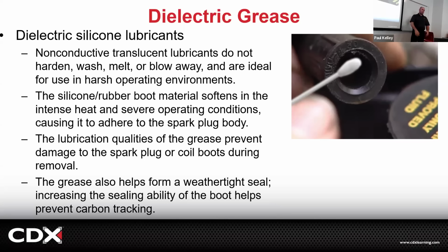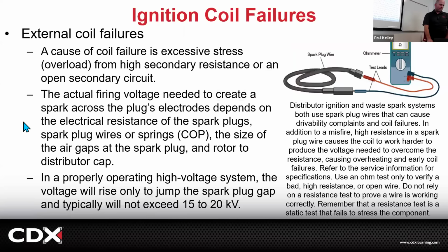So sometimes I see in the forums, people are like, oh, if you got a bad connection, take it out and dielectric grease it and put it back together. It's like, that doesn't make a better connection. If you were to do that, it makes it worse. If you were to do that before, that would have kept the water and the corrosion out and it would maintain a better connection. Yes. But once the connection's corroded or rusty or whatever, the dielectric grease ain't helping. Okay, makes sense? We have to actually make sure the conduction is good first. Cool. And that's pretty much what we're saying.